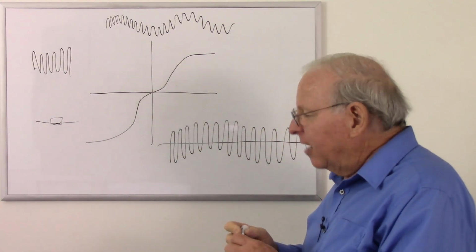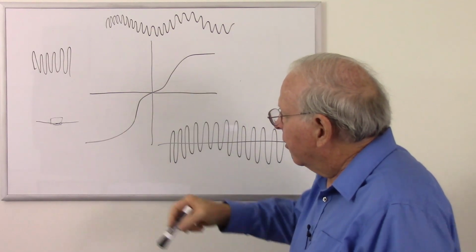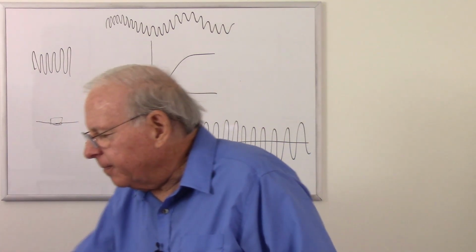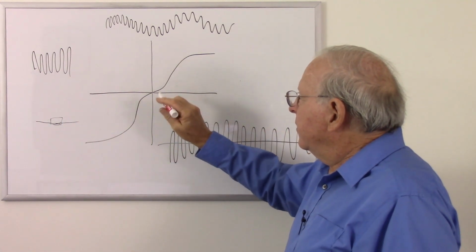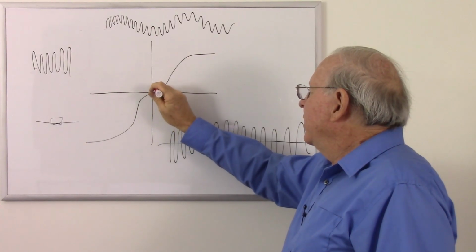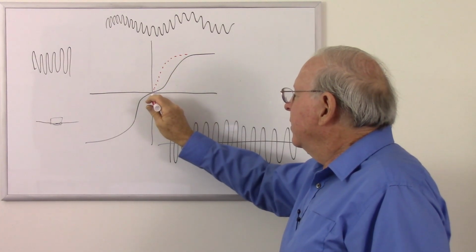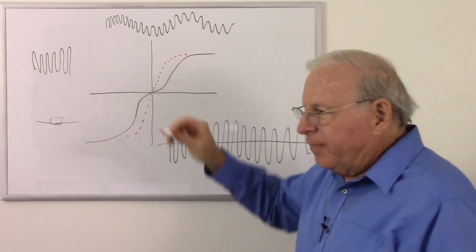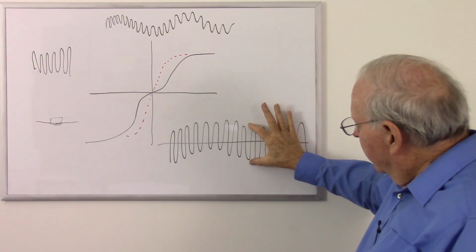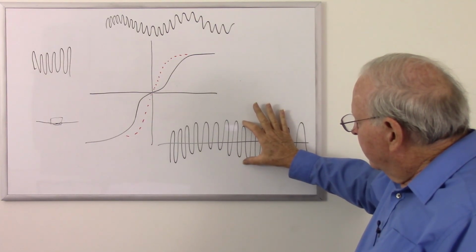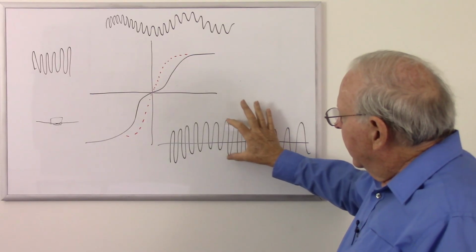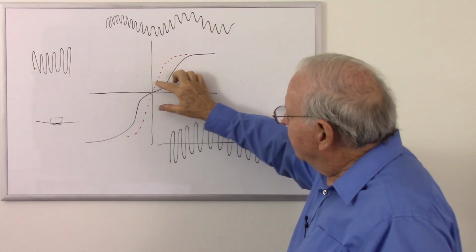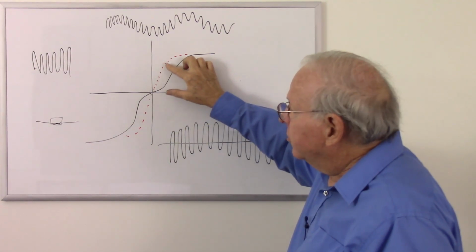So we end up with what's actually on the tape does not follow this transfer curve, but actually follows, if we draw the whole thing, let me draw this in red just to make it stand out. What's left with the AC bias is, if we follow the same curve, does not follow the transfer curve, but ends up that if we're right here, where we get equal amounts of magnetization on either side of the 0 line, it's going to be completely demagnetized. But if we're offset a little bit, it leaves a little residual. And notice there's no distortion.